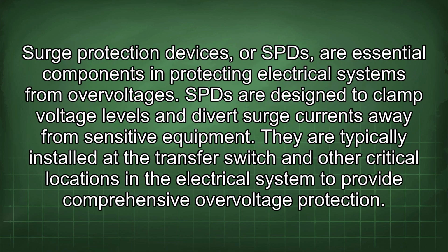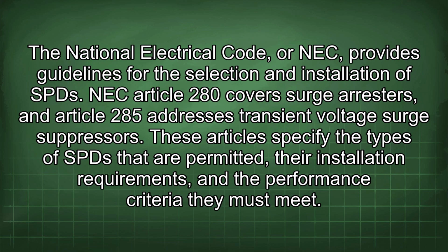Surge protection devices, or SPDs, are essential components in protecting electrical systems from overvoltages. SPDs are designed to clamp voltage levels and divert surge currents away from sensitive equipment. They are typically installed at the transfer switch and other critical locations in the electrical system to provide comprehensive overvoltage protection. The National Electrical Code, or NEC, provides guidelines for the selection and installation of SPDs.